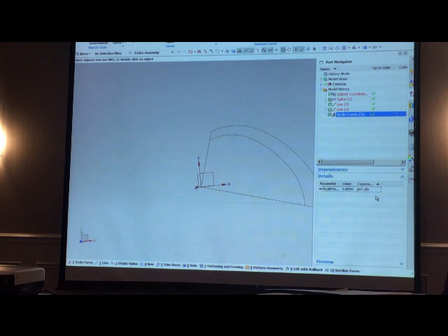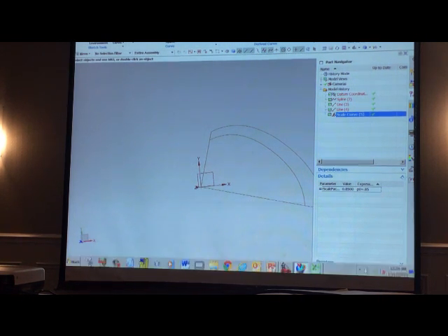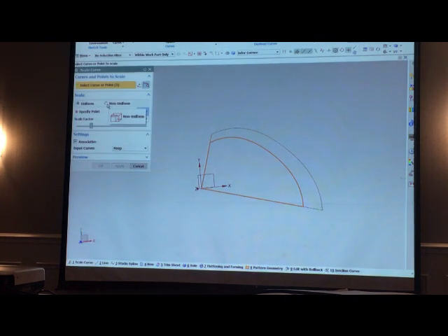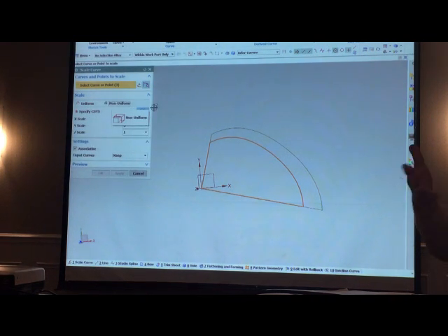So now we can scale curves, and it works in 3D. It doesn't have to be limited to 2D. It just scales it relative to the origin. And if you noticed in scale curve, you have non-uniform as well as uniform. If it goes into non-uniform, you can apply a separate scale in each of the 3 primary directions. So you do have full control over curves that get scaled. That should be useful to everybody. So there's non-uniform and there's uniform.